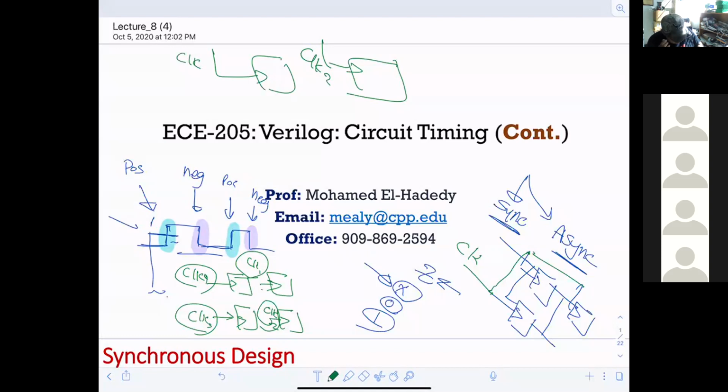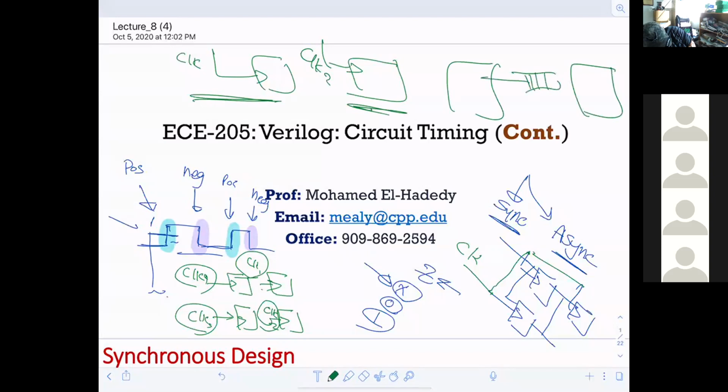Right? Because this is running at one speed and this is running at a different speed. How are you gonna deal with that, so this one will not spill data out? So basically you have a circuit here and a circuit there, and then you will build here a buffer. This one will be with this clock and this one will be with that clock. This way, you will be able to move the data from this one to that one without any problem. That's why when I started my discussion today, I started out telling you about this buffer thing. That makes sense?